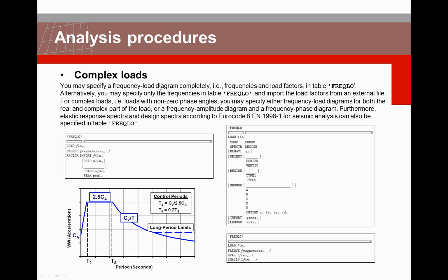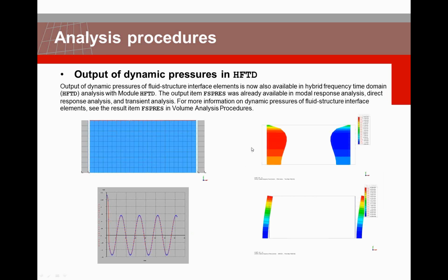This can be defined by hand, but we can also define these frequency loading amplitudes with reference to Eurocode 8. For dynamic analysis in the hybrid frequency time domain application, we can now also generate the output of the dynamic fluid pressures, how they act at certain time steps on the structure.